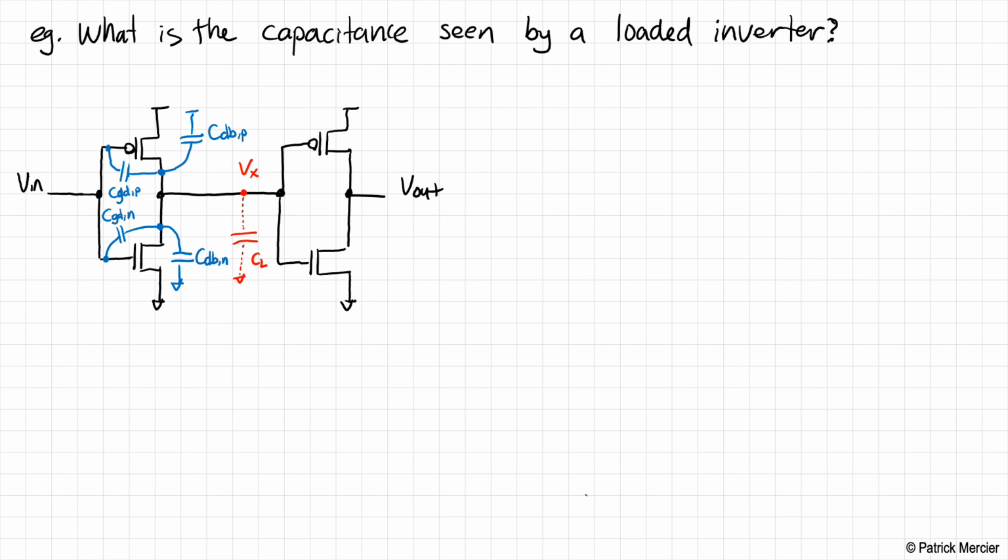In digital circuits, they also introduce problems, but we'll figure out how to deal with them. Now, technically, we also have some capacitance between the source and the bulk, CSB, but we can safely ignore these because they're grounded on both sides, and so therefore they don't contribute any losses or they don't operate in the circuit. Okay, so we can ignore these.